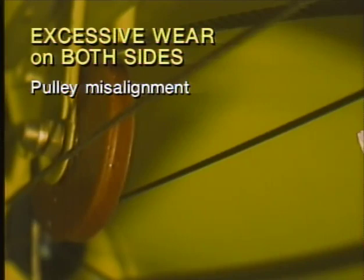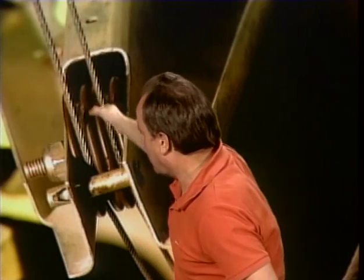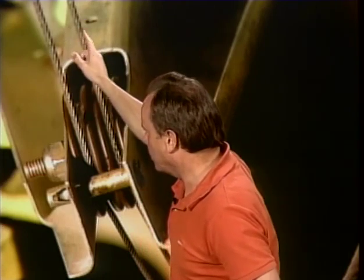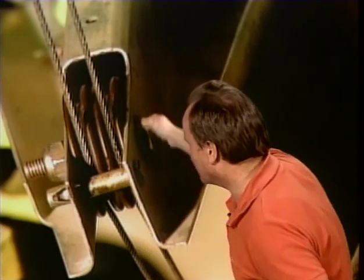Now, let's talk about inspecting the controls of an aircraft. A satisfactory method of inspecting control cables for broken wires is to place a piece of cloth around the cable and run it back and forth over the length of the cable. And what happens is, if you get little broken wires, it'll catch on the cloth. Now, another way you could do it, not recommended by the FAA, is just run your hand back and forth and just check for blood in your hand. Now, I think I'll use the cloth instead, if you don't mind.